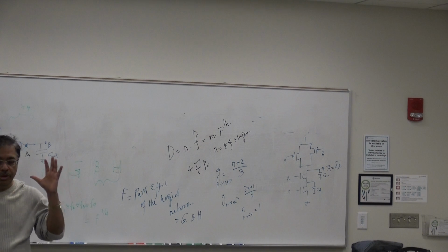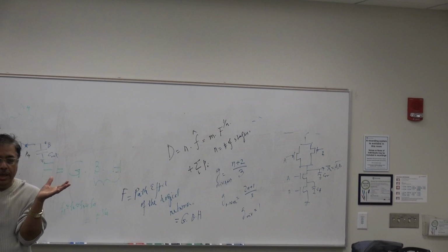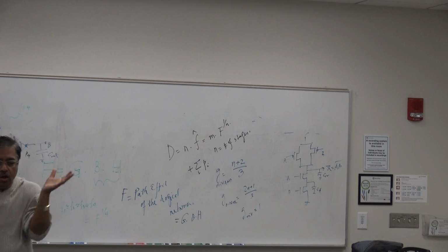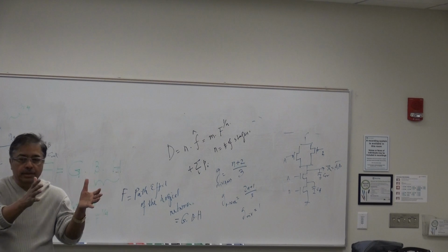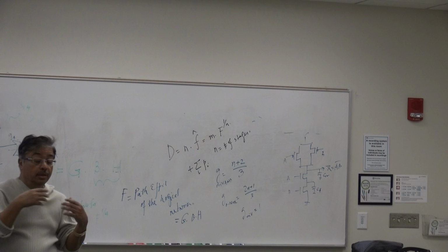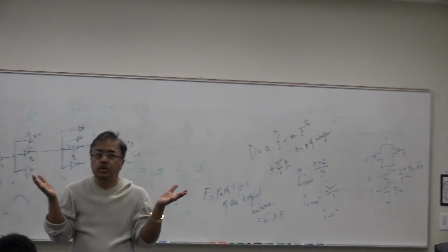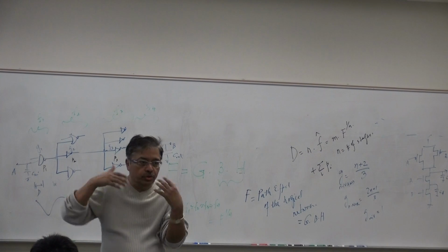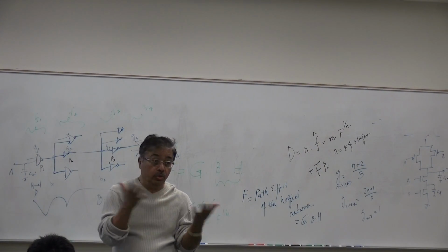You have to create some amount of abstraction so that you can solve the problem in 90% of the cases, and the 10% of the cases, because of this internal node capacitance and so on, you later go back and use SPICE and try to take care of that and find out the better one.